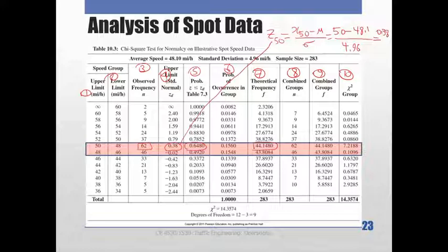Where did we get this probability of occurrence in that group? So basically in that group, I need to look into my speed between 50 miles per hour and 48 miles per hour. In order for me to do that, now I need to get the speed that is less than 50. We just calculated the probability of the speed less than or equal to 50 miles per hour, which is 0.648 from the standard normal tables. And what is the probability of having the speed actually?